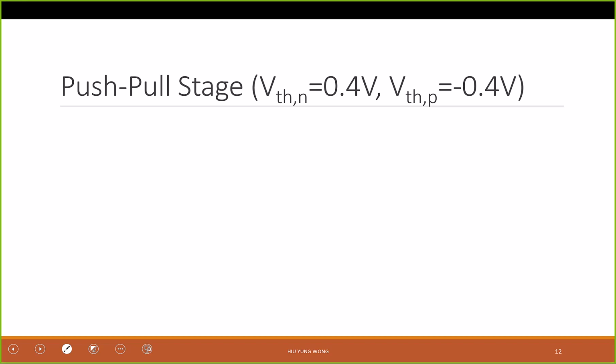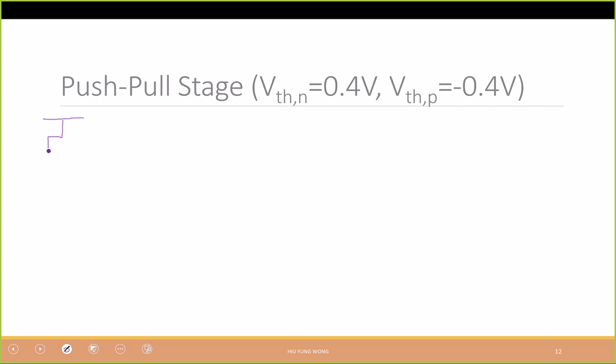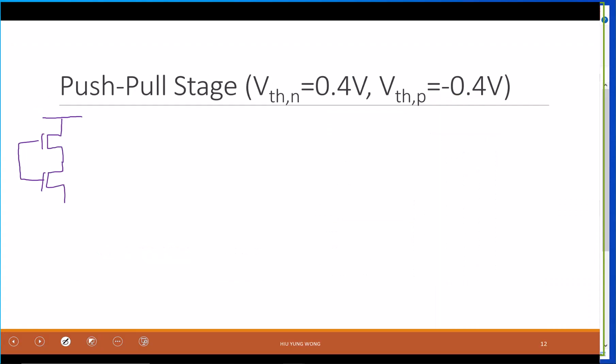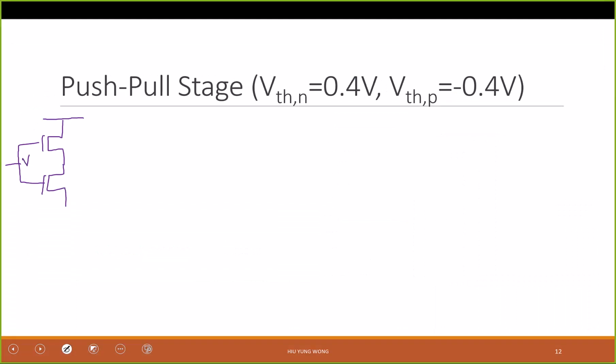You see the limitation of the source follower output stage because of the distortion at the end, right? Then naturally, some of you may think, well, the reason that I cannot go down is because I have NMOS on the top. What if I have PMOS at the bottom? Then maybe I cannot go up. Then what if I have both, right? So this one, you can spend time to think about how you can come up with these circuits, but it is just given to you here, that how people use it, and then let's analyze to make sure that this works. This is V in. And let's look at this carefully.